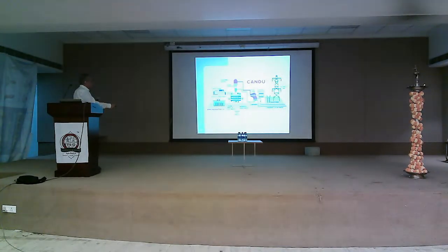Heavy water goes through this, gets heated, and goes to the steam generator, and here light water comes, gets converted to steam, and the steam goes to the turbine. And this is sea water, which condenses the steam here in the condenser. Water goes back, so this is a closed loop. So there are three systems. First is the heavy water coolant here. This is demineralised water. And this is your sea water.